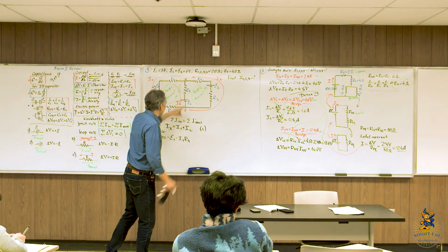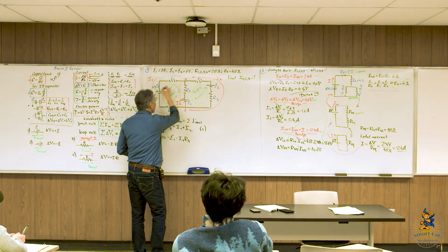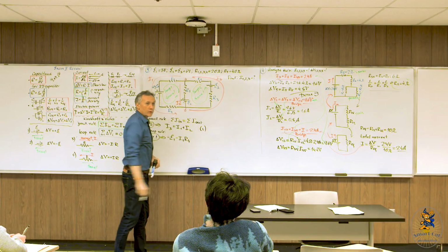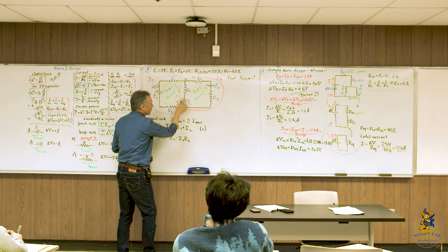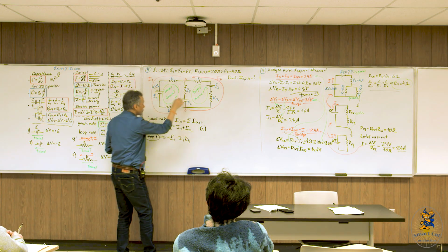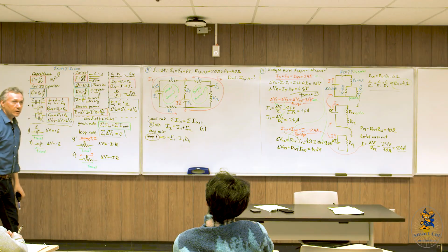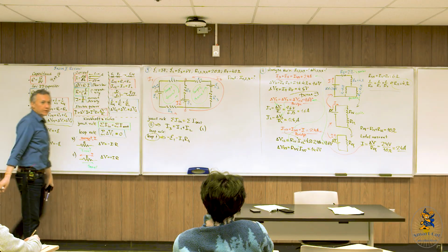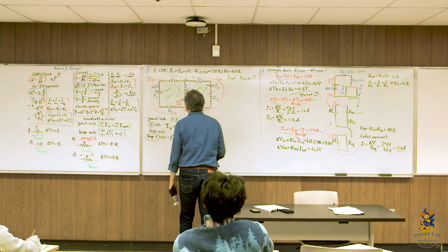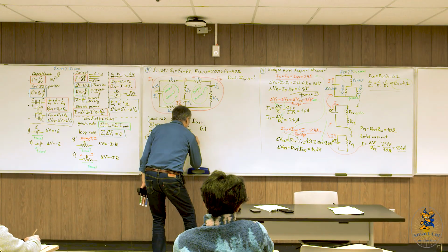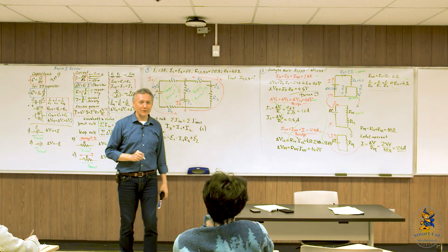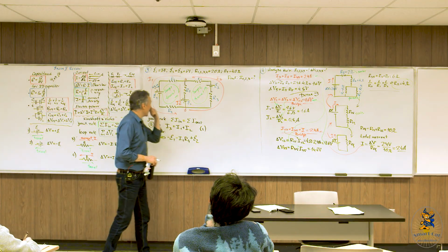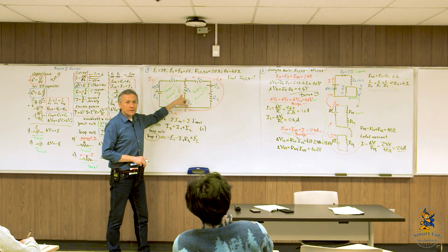So we're traveling from minus to plus. You see the loop direction: we're still in loop number 1, so we're moving counterclockwise. Across this battery we're moving up, so from minus to plus. As a result, the contribution is plus. From minus to plus, the contribution is positive. Electric potential increases across the battery. So plus EMF 2. I should have started in front of battery 2, then I would have a positive number at the beginning of the equation.